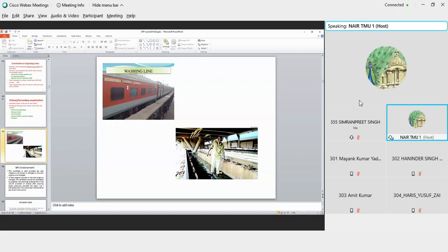and the Bombay Rajdhani, after giving primary attention at Bombay, goes to Delhi. So we don't want, because Rajdhani being a more stressed train and a more important train, we say that we will take Rajdhani on the pit again and do this complete examination before it starts this reverse trip. So that is called secondary maintenance at Delhi. There is no difference between primary maintenance and secondary.